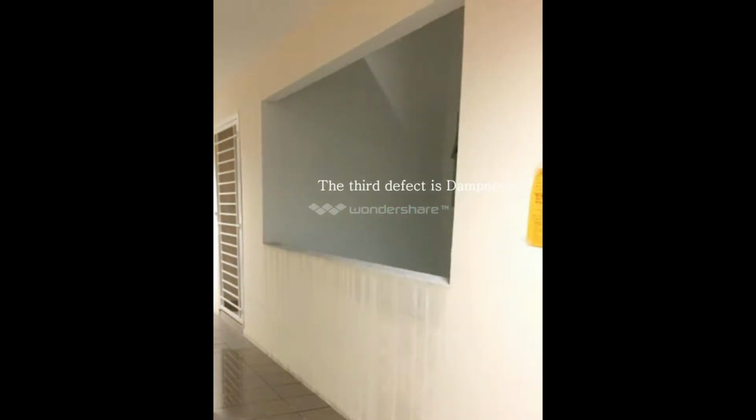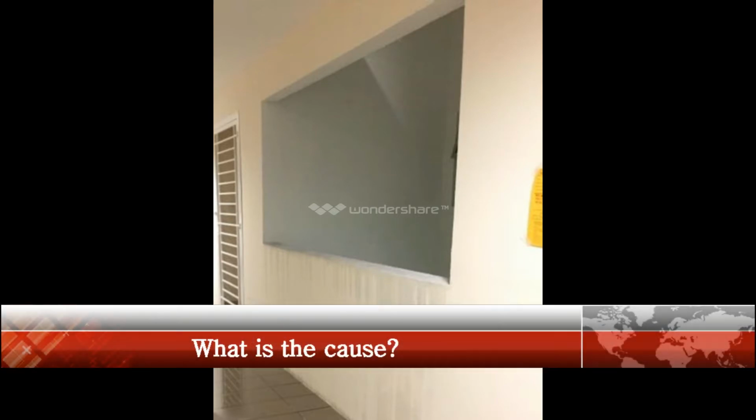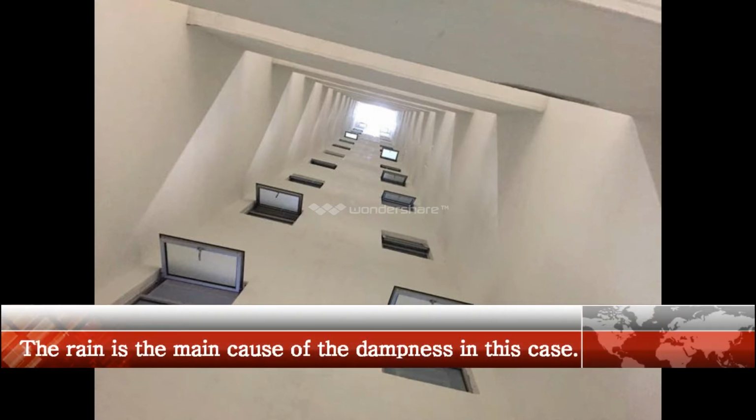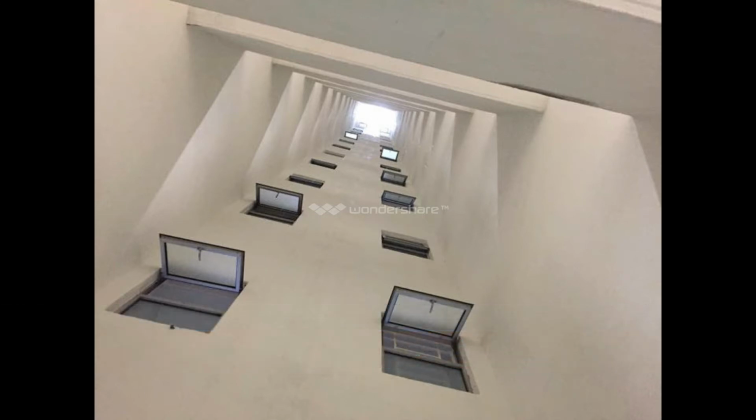The third defect is the dampness in the wall. Structural dampness is the presence of unwanted moisture in the structure of a building, either the result of intrusion from outside or condensation from within the structure. A high proportion of damp problems in buildings is caused by condensation, rain penetration, or rising damp. Here the rain is the main cause of the dampness. The rainwater easily reaches the affected area because this area doesn't have a roof gutter.